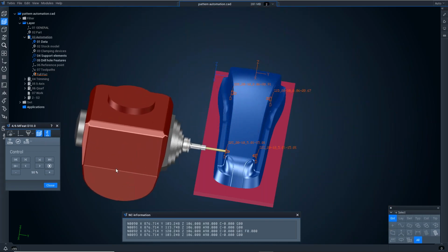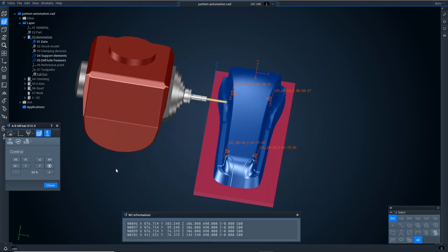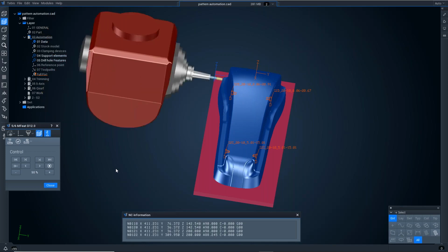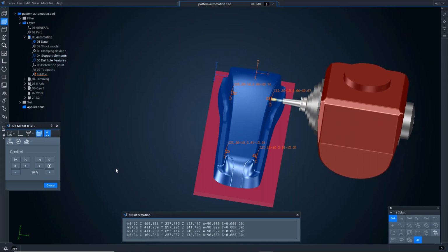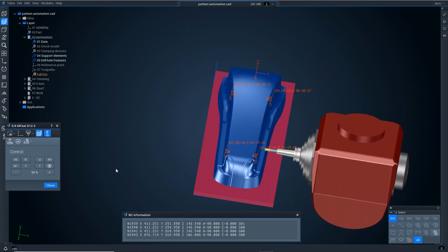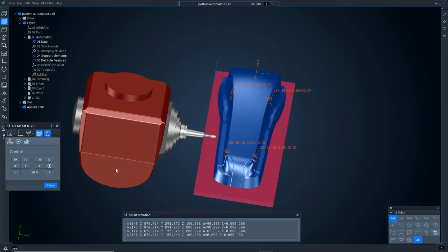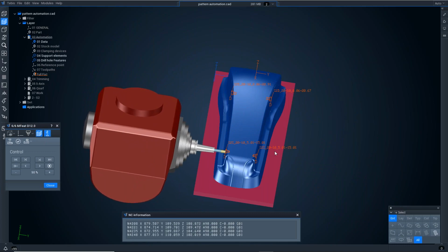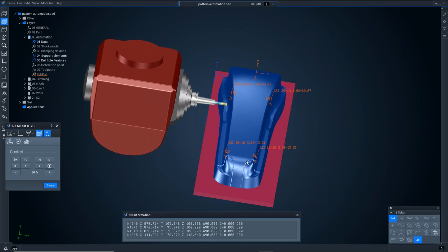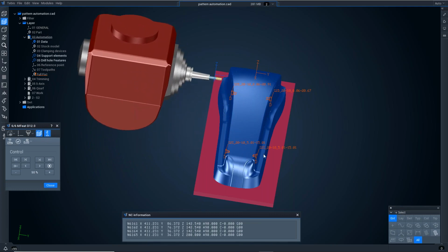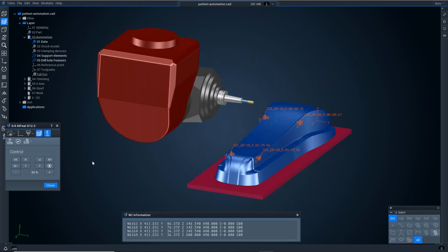And one thing to also bear in mind, because we're all within a singular machining operation, even though this is multiple programs, all of the connections between the tool paths are fully collision checked. Therefore, we're not just checking on the job like most software will do. We're actually checking the toolpath off of the job to ensure that we've got no collision going on whilst we're moving between operations. As I'm sure you can appreciate, if we go from this hole here to this hole here, as we've just seen, it'd be very easy to go through the component. Because Tebis has done this all in a feature set, it knows to go around the component and automatically avoids the part so as not to create a collision.